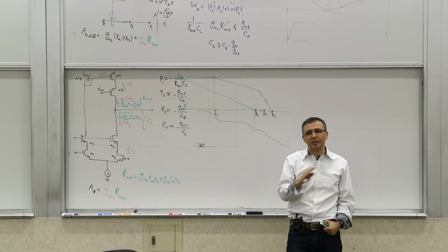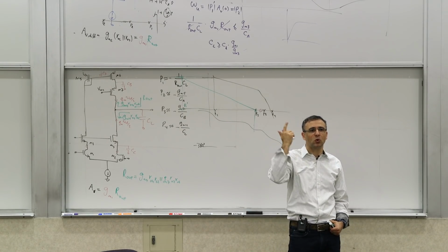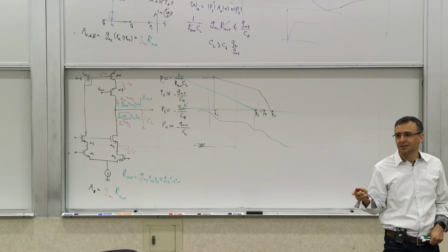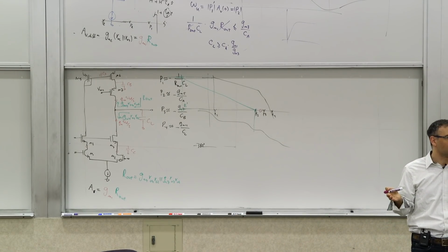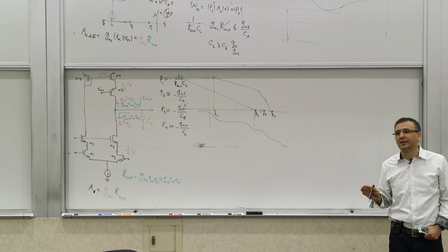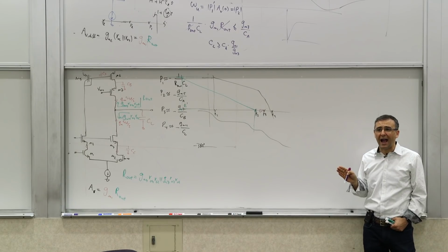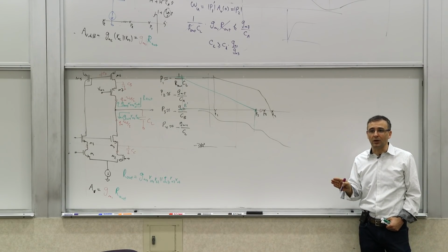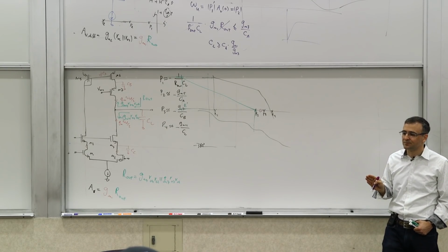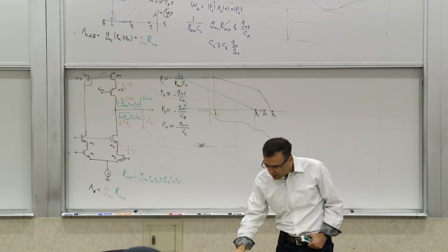Because one pole you can always handle, right? We saw that the first order system is almost always stable. Well, it is always, for all sorts of nonlinearity even. So your first pole is not really what matters, and you may sometimes intentionally make it even lower. It's the second pole that would affect you a lot. And that's something to keep in mind for this kind of system.